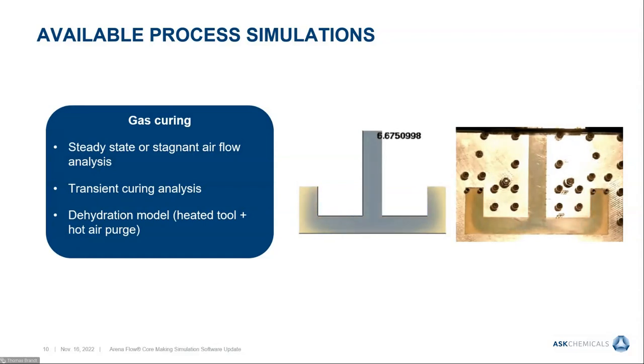Additionally, modeling is a gas curing. See how the gas front makes its way through the core, and again, simulation compared to reality. In addition to the traditional airflow model, we have added dehydration, so now we color the full spectrum of curing.